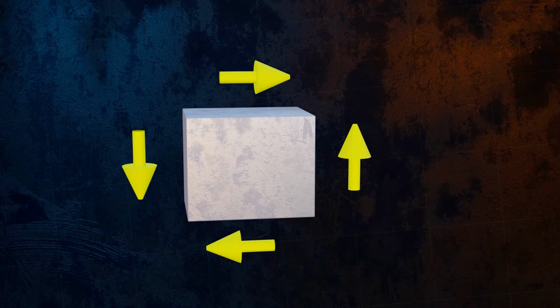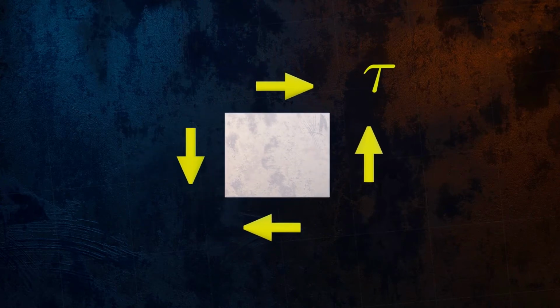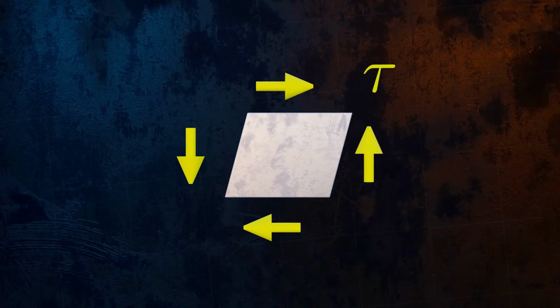We can understand shear stresses by looking at the stresses acting on a small element within our bar. We have a shear stress on one face of the element, but the element needs to be in equilibrium, so we must also have shear stress on the opposite face in the opposite direction. And to maintain rotational equilibrium, we must also have two-dimensional shear stresses, as shown here. These four stresses all have a magnitude equal to tau, and define the shear stresses acting at a single location. Shear stresses cause a rectangular object to deform like this.